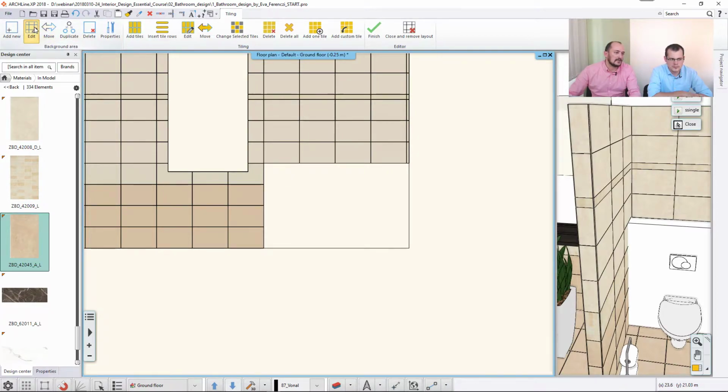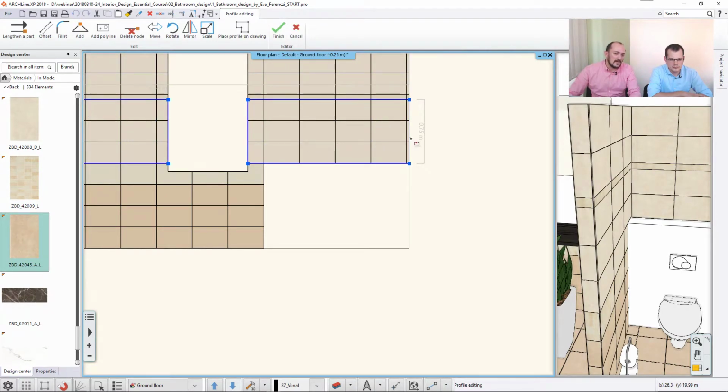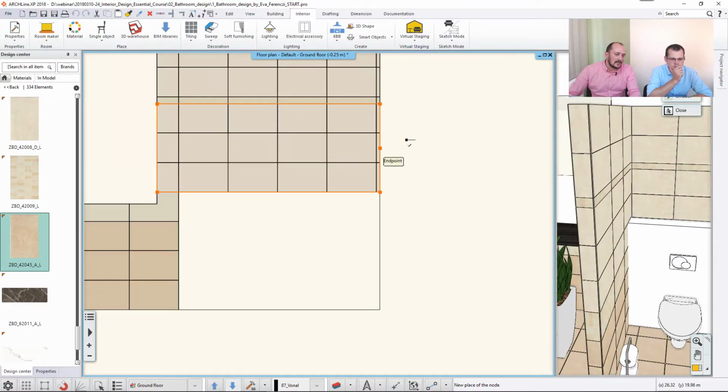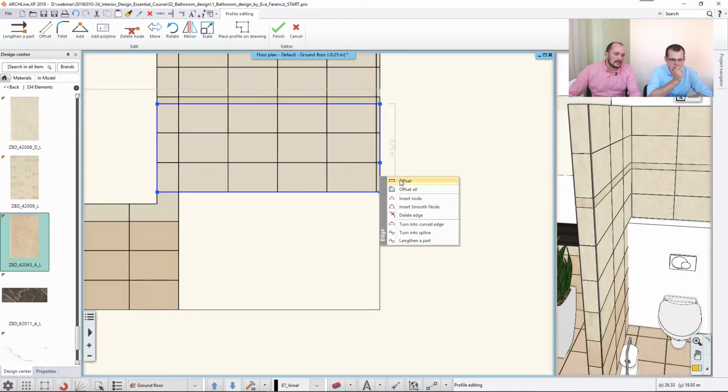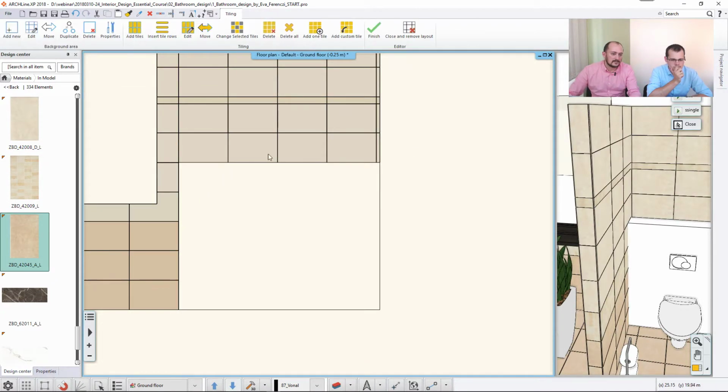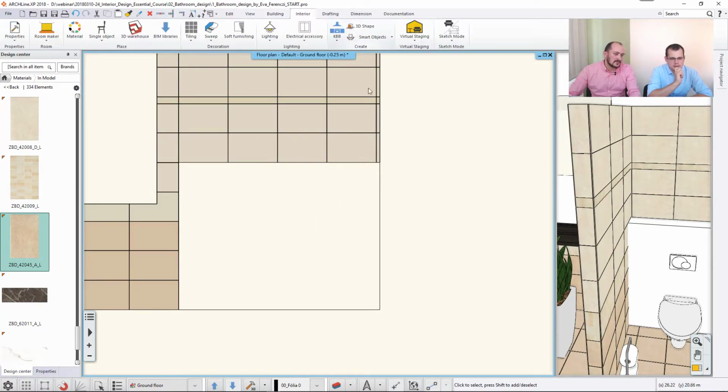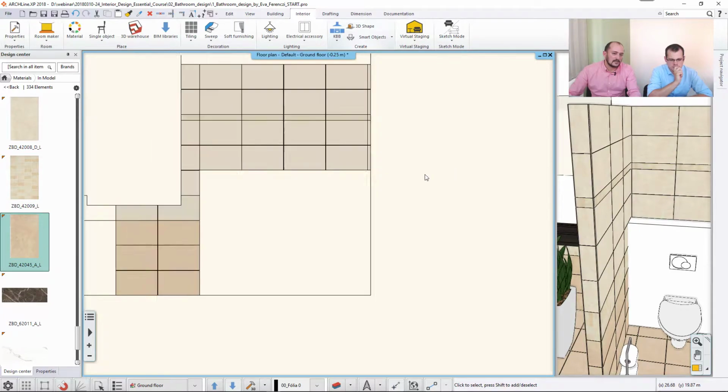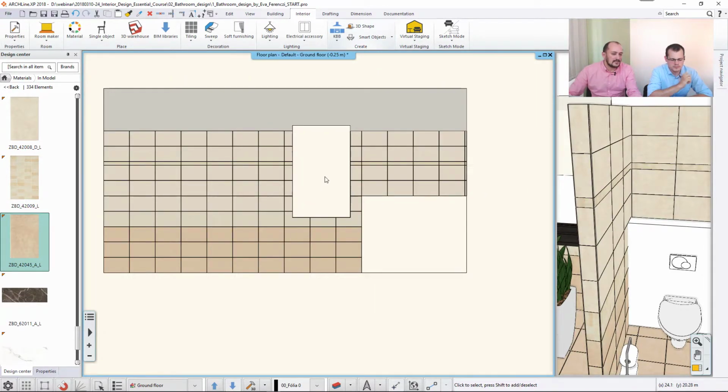So when I click here, edit this one, I don't want to completely have this offset here, but instead I insert a node here, click here, click move offset, and then enter and enter. This is how I can remove that part. Then when I click finish, the software finishes editing the layout, and I can still keep the layout for any sort of purpose. I can use it for measuring distances, adding detailed descriptions, labels, or anything else.